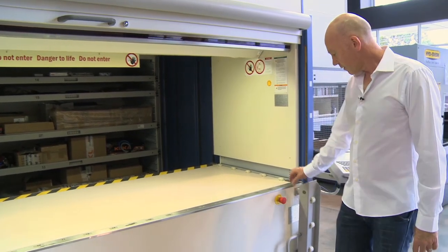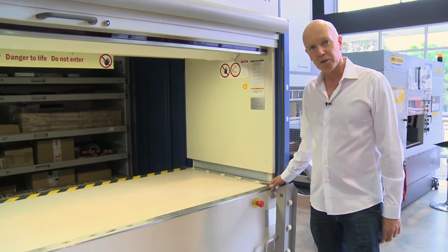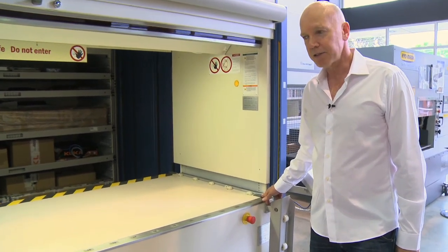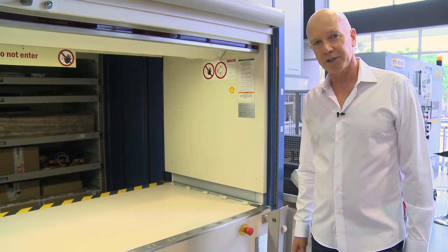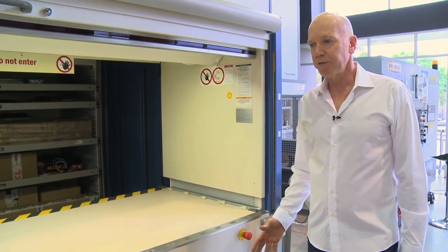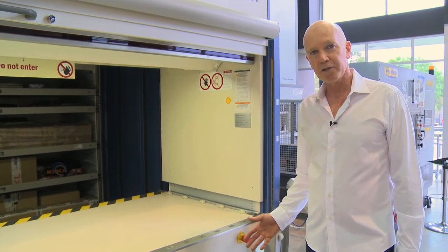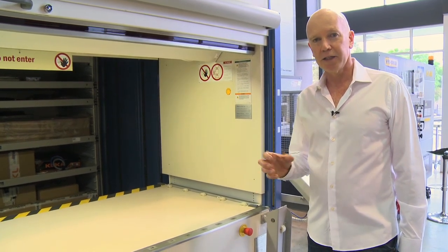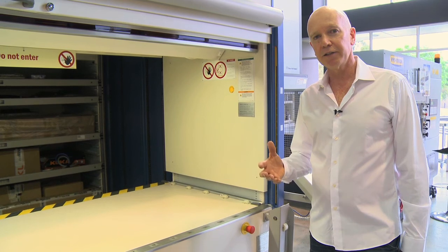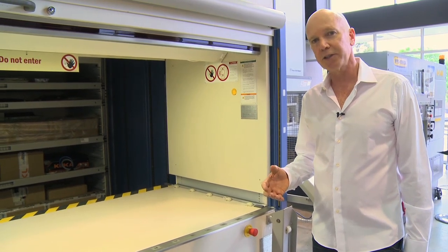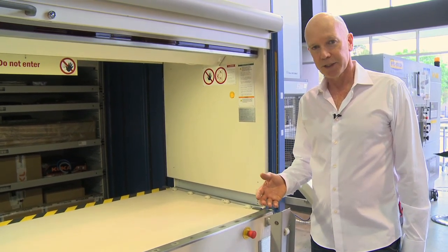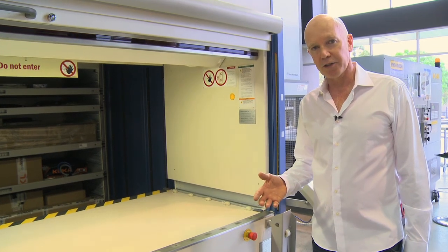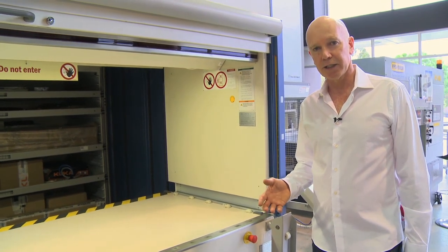Here, for example, is a small proximity sensor, but this has been replicated on the other side of the machine. If something fails, you'll get an error message on the control panel. The screen will go red, indicating to the operator that you have experienced an electrical failure. At that point, we can go to the control panel and activate the redundant system.